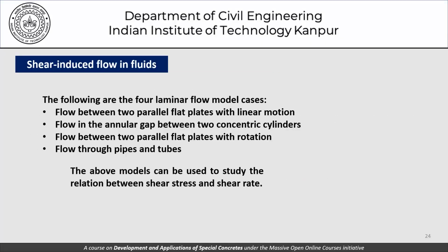As far as shear induced flow in fluids is concerned, there are four models which are often used: the flow between two parallel flat plates with linear motion, flow in an annular gap between two concentric cylinders, flow between two parallel flat plates with rotation, and flow through pipes and tubes. These models have been used to study the relationship between the shear stress and shear strain rates.